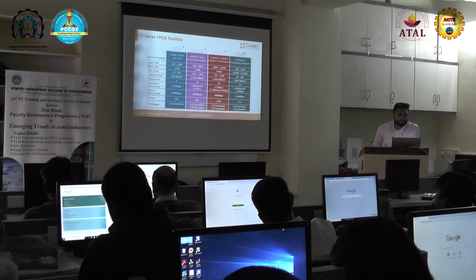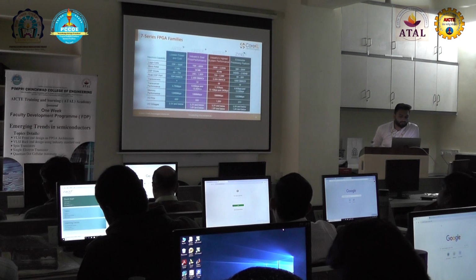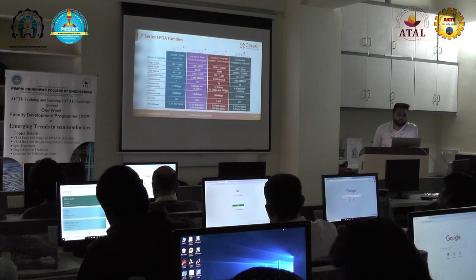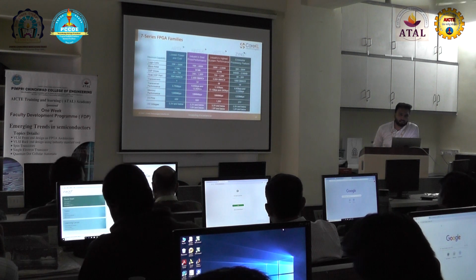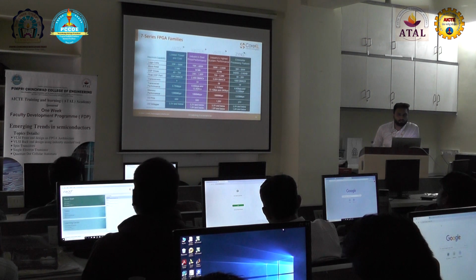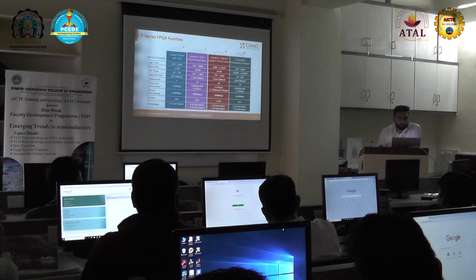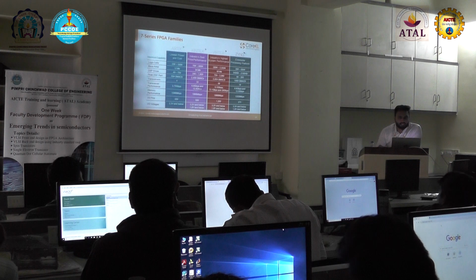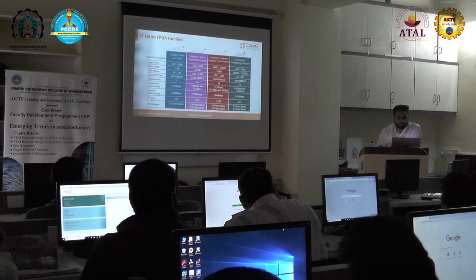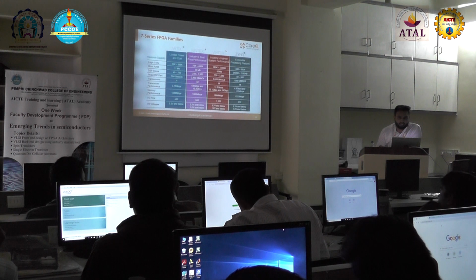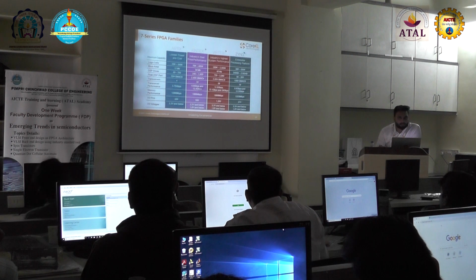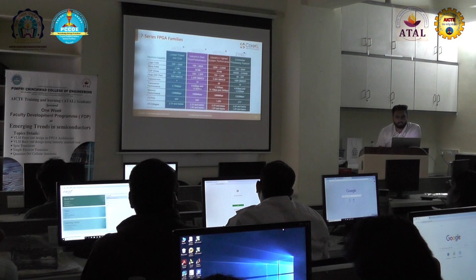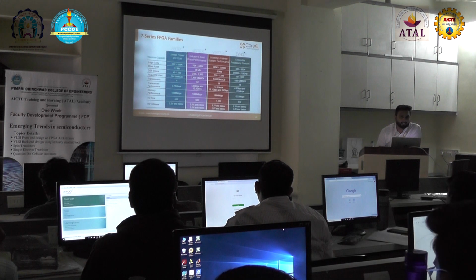Okay. So in UltraScale, you will get Kintex, Virtex, and Zynq. Artix will not be present in UltraScale. And those UltraScale boards are 20 nanometer technology. And when it comes to UltraScale Plus, you will have Virtex and Zynq. Only these two families are present in the UltraScale Plus series, which is 16 nanometer technology. Right, after that, the latest one is Versal ACAP, which is 6 nanometer technology.